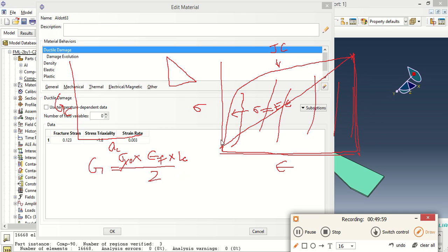So I recommend that if you have a load displacement curve, you can find the energy inside the curve. And the energy inside the curve can be obtained very easily. You can use the trapezoidal formula. Obtain one point here, obtain one point here. Okay, and what does the trapezoid formula say? Area of trapezoid.